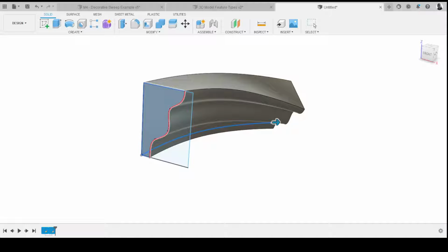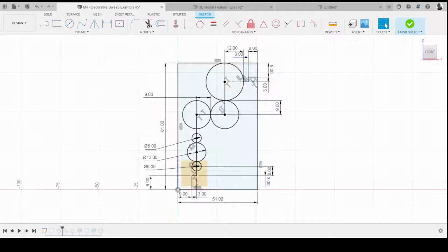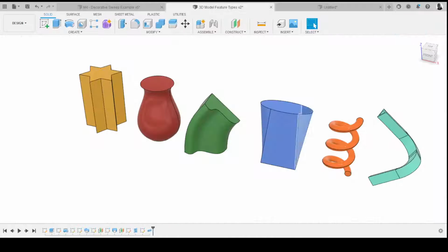I've done a load of stuff with variable chamfers along a curved edge, and a swept cut was really useful for that. The classic one used to be if you ever wanted to model the old-fashioned telephone cables, you know, the helical cables. That's an obvious type of sweep. There is now, wonderfully, a shortcut for that in Fusion, which is, you've got a coil function, so you can do just standard coils in the coil wizard, so you no longer have to do that. But that's a classic swept shape, that kind of thing.